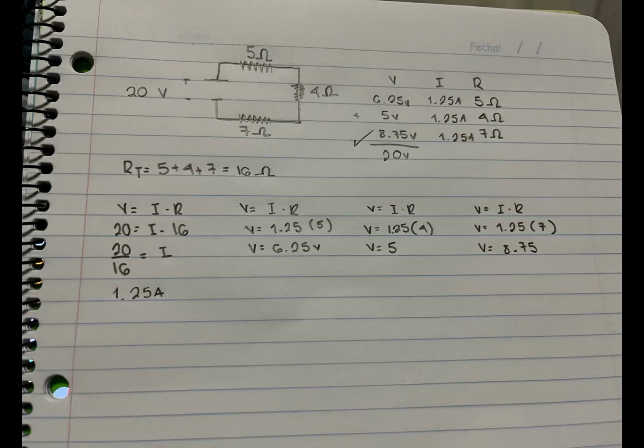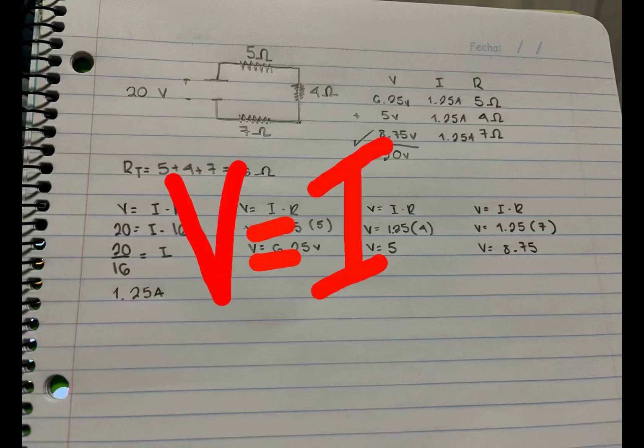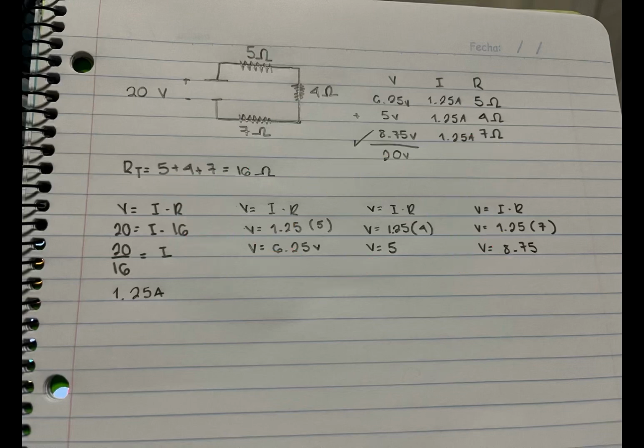After we do that, we will find the amount of amps that pass throughout the whole entire circuit by using Ohm's law. V equals I times R. We substitute for the values. After that, we have a battery of 20 volts, and if we add the ohms, we will get the total amount of resistance, which is 16, substituted for R. We then divide 20 over 16, giving us a total of 1.25 amps passing throughout the circuit.